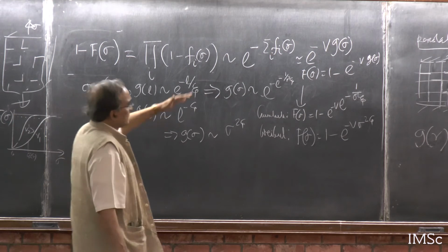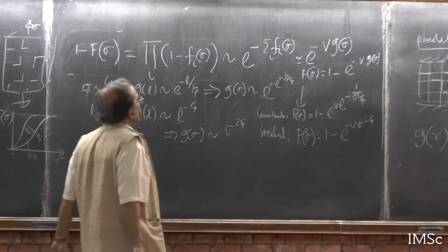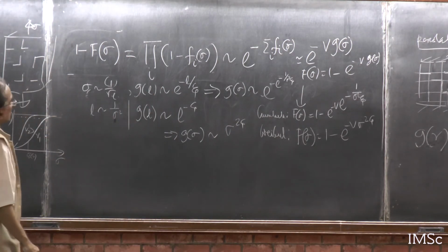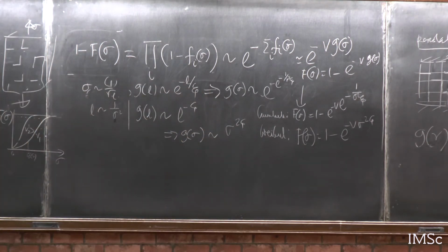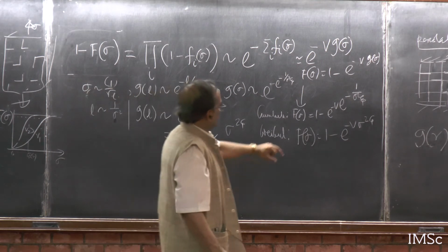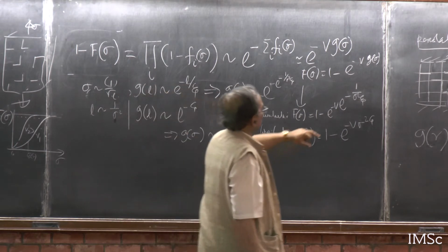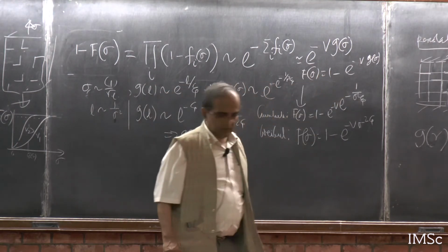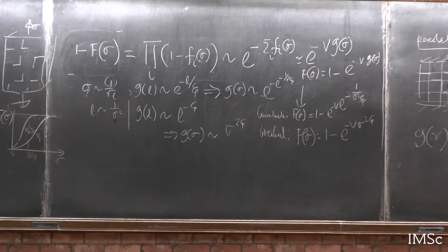And since engineering mechanics has a very good fit either to this or to that, you can get now using some of this scenario, and you are still assuming that they are not overlapping. And you can see that log V is very important. In the Gumbel form, log V is very common because V and sigma are exponentially related, so sigma goes as 1 upon log V for failure.